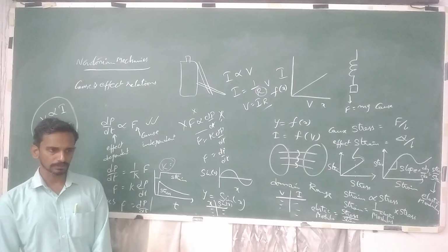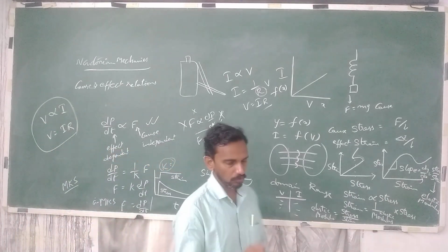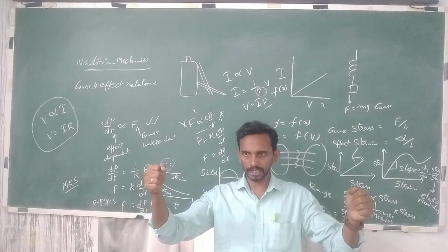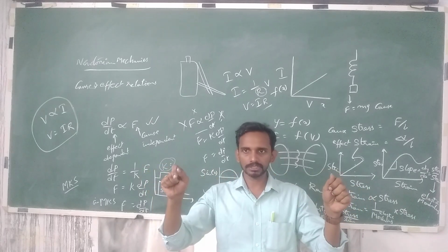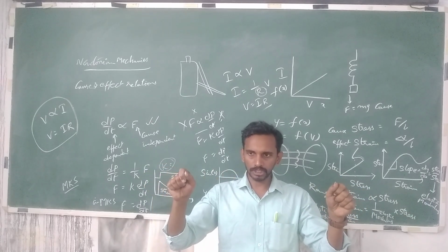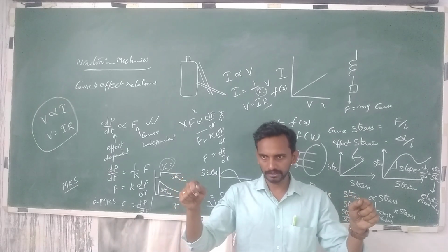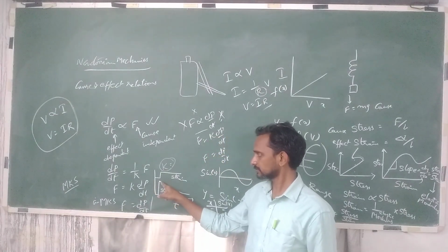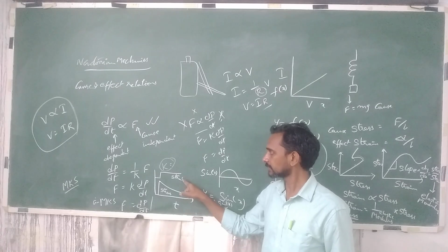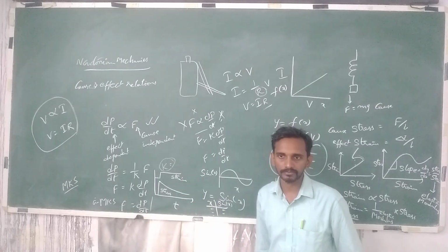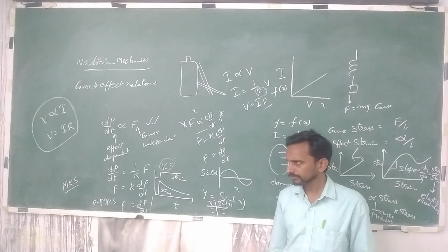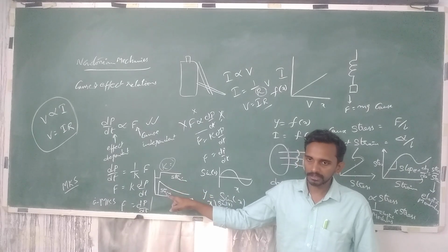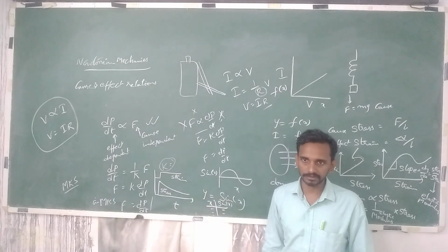So, strain relaxation. What happens once I start pulling a rubber band and wait for some time? Once the stretch becomes used to that rubber band, or once it may get permanently deformed, you don't need to apply the same amount of stress. You can reduce the stress by keeping the strain constant. So now what is the study here? How much stress is required to keep the same amount of strain is the study here.